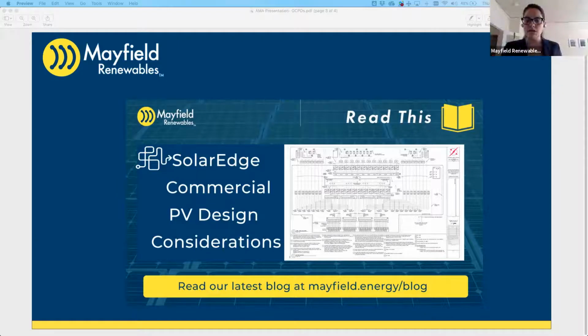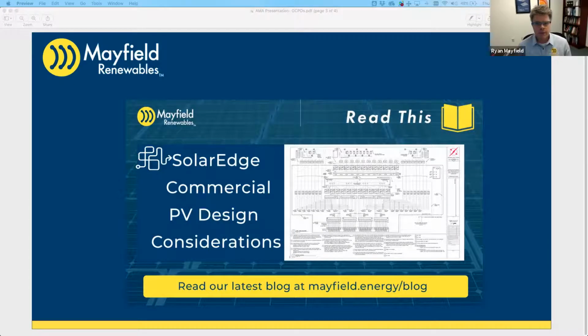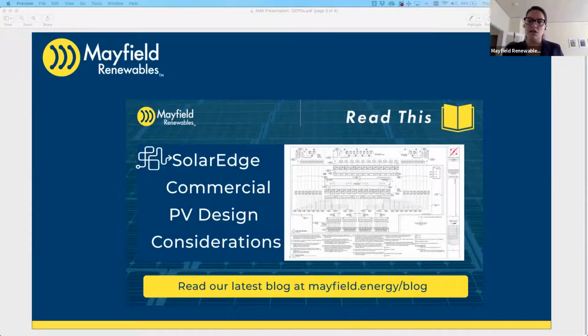So I was just going to ask, but I think you already answered it. In terms of affecting, it sounds like this is a rule that will require larger conductors. And how does that affect installation cost? It sounds like it's minimal. Yeah, I would say minimal because it's saying 6 gauge minimum, but the reality is we're probably going to use that anyway.